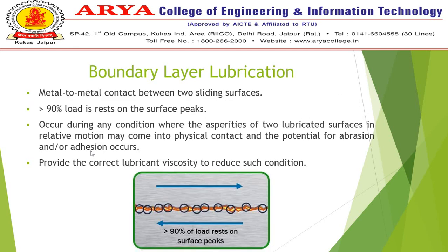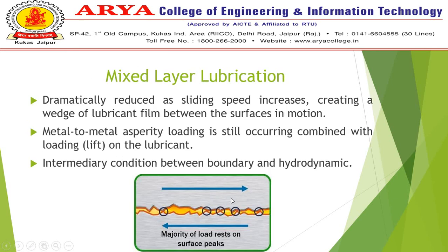So in the previous one there is a sliding between two mating parts, the first one is this mating surface and another is this one. So these two mating parts have opposite velocities of sliding in opposite directions. But in this, the majority of the oil is making a wedge. Wedge means a constant layer between two mating parts.